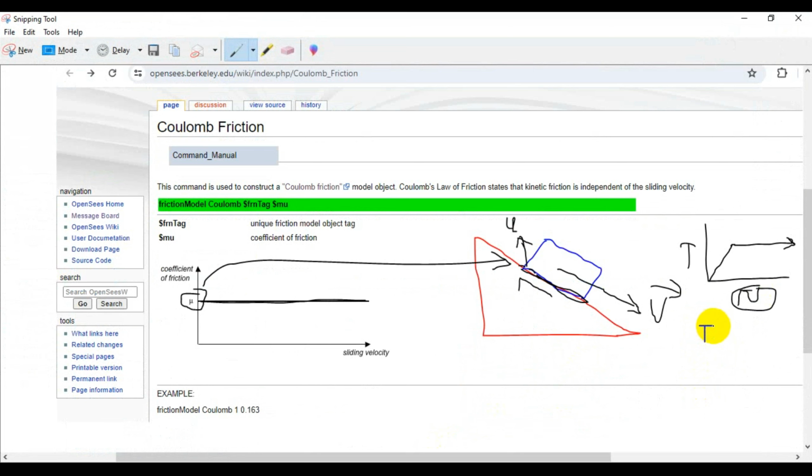The shear force will be directly related to the normal force in this stage, and as soon as the coefficient of friction is introduced, it will transfer to this stage here. So with increasing sliding velocity, the transmitted force remains constant at the friction resistance level, nu multiplied by the normal force, and this is because the model assumes constant friction during sliding here.